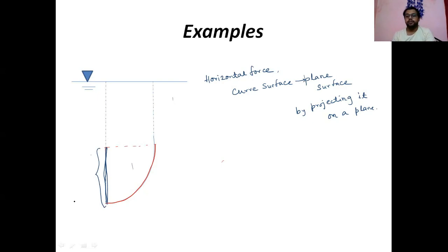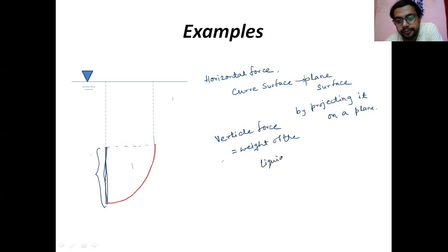What about the vertical force? The vertical force will give you the weight. As in the previous discussion, the vertical force is the weight of the liquid column supported by the curved surface up to the free surface.